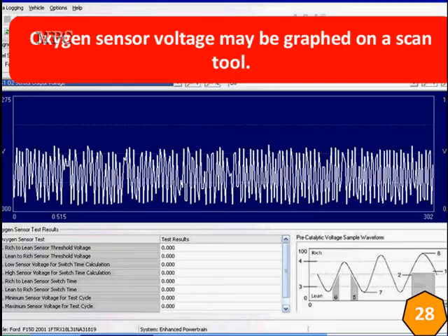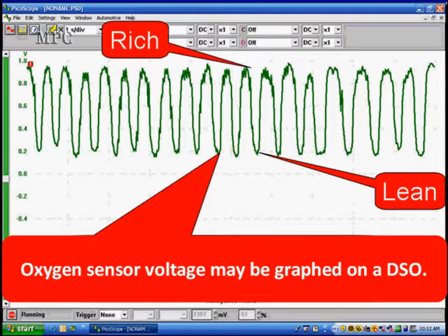302-second recording we made looking at this particular oxygen sensor. It looks very much like the pattern we had before. So this is a good starting point. Now we're going to get down very specific and talk about the patterns. Now once we have ascertained we have normal fuel control, we start judging our rich and lean. Now typically we see it oscillating between 0.2 and 0.8 volts. Very much like you see happening here.